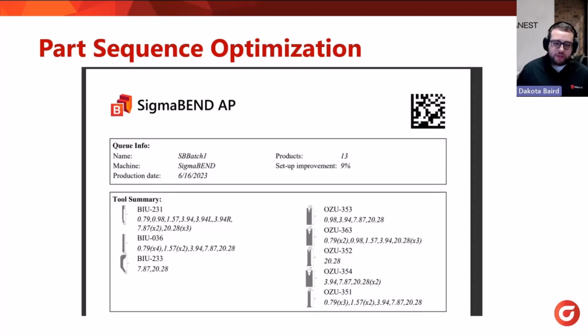So if we analyze these particular 13 products that we had, the various different quantities, and the estimations on the bending time and setup time, we were looking at about an hour to program this entire job from the time estimates. On a per part level, that was about 30 seconds per part based off of the quantities that we had. In a normal kind of standard environment, we can estimate that manual clamping of tool changing and things like that is about 10 minutes for a program.